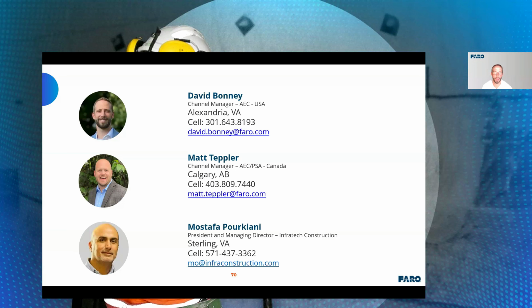Yeah, so just a comment there. Of course, Mustafa was showing you a lot of scans from the outside of a building, but yes, these scanners are absolutely used for internal, in this case, a hospital. We've scanned quite a bit of hospitals. Just keep in mind that all laser scanners have their use cases, and a mobile laser scanner is going to be a little less dense than a terrestrial laser scanner. So to answer your question, an Orbis scanner, for example, will get you LOD 250 to 300, whereas if you need fine detail in the piping and things like that, you really do need a terrestrial laser scanner with a lot more density.